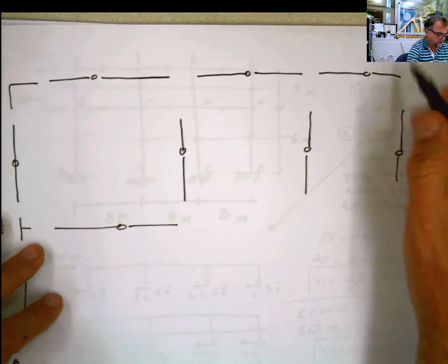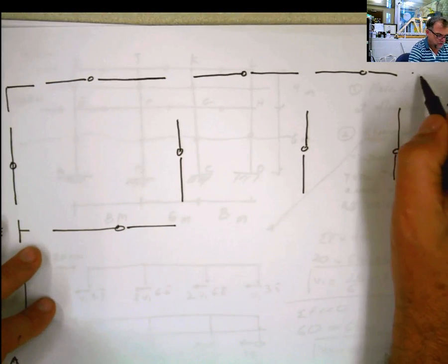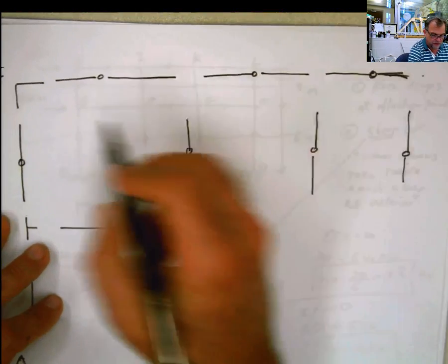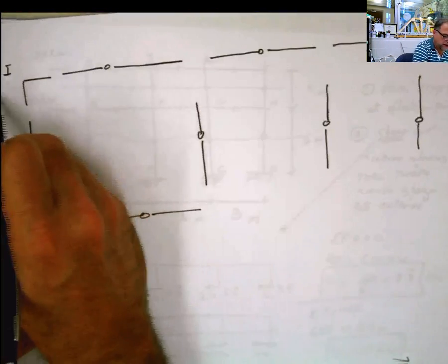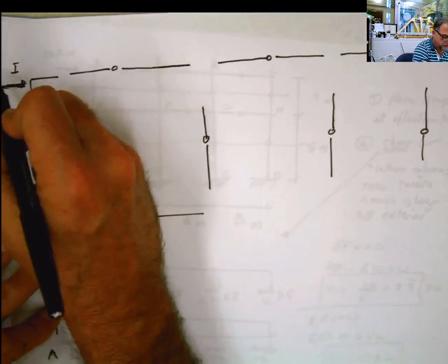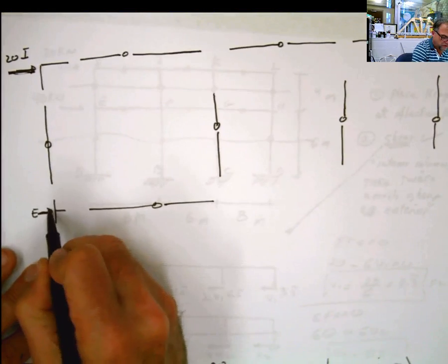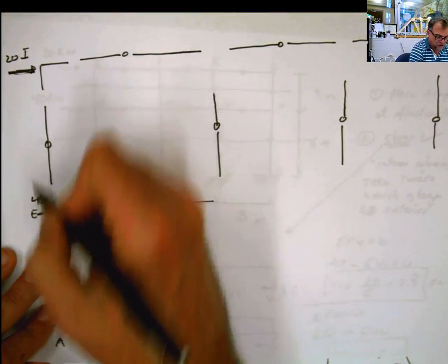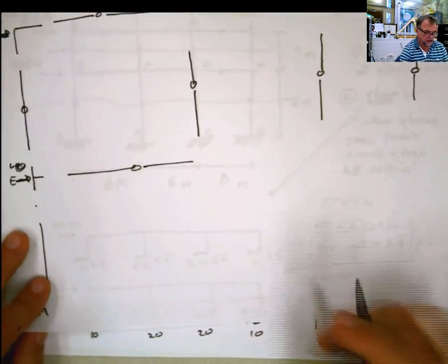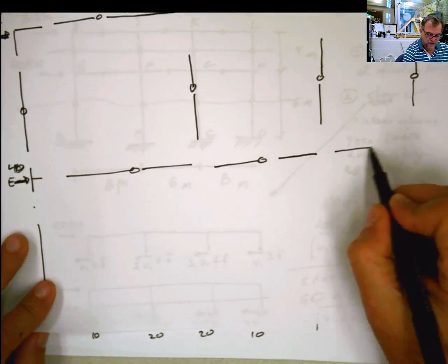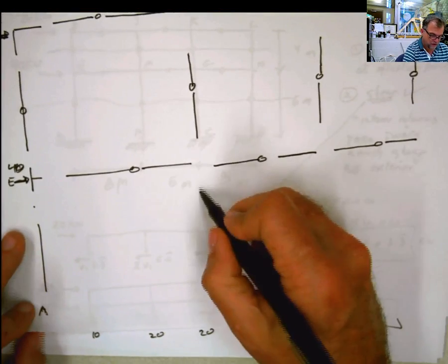Of course, you have the same joint in this other part, but the analysis of the joint in this part is not important because I don't have any concentrated force. I need these definitely because I have that force of 20 there, and I need these definitely because I have that force of 40 there. That's why I'm isolating the joints in this part and not in the other parts. So then you have that, and then you have these, and then you have the columns here also.